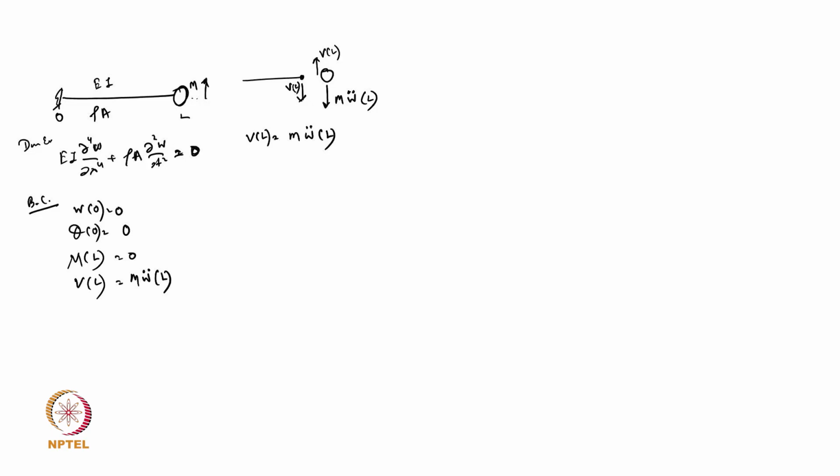That is why, if you see, exactly when moment is 0, there is a bending strain, means bending strain will be 0 when the curvature becomes 0, but you will then have the third derivative, this will be quite important. The way I generally try to do it, if you have an axial type thing, it is better to do the force balancing, because force balancing we all know how to do, like with the bending moment diagram and shear force diagram, how we plot them.